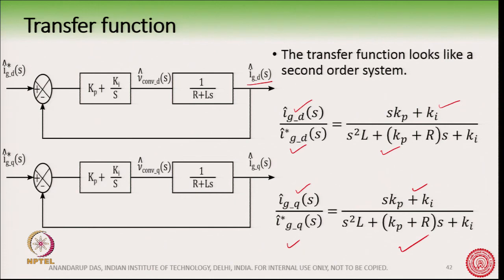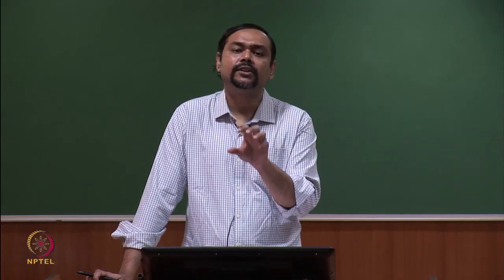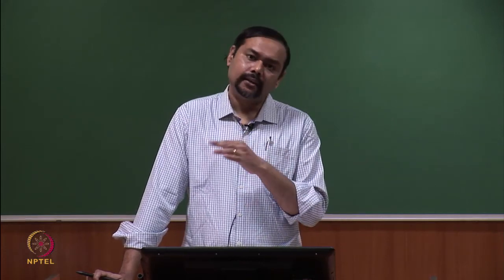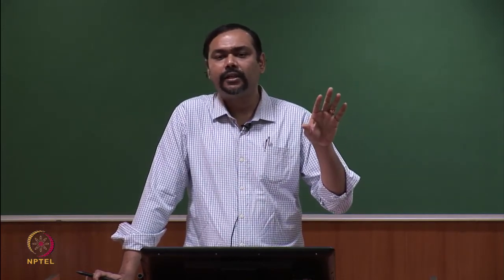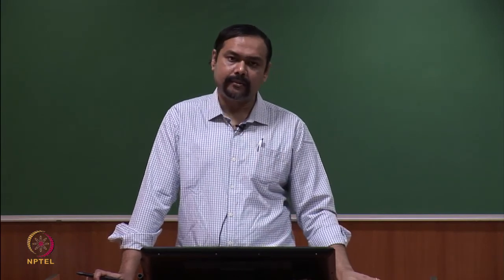So, we can go one step ahead and go into a DC domain with the help of the Clarke and Park transformation, and with that DC we can apply our linear control system theory. We give a small AC perturbation to these DC quantities, get a small signal model, apply the transformation and get it back into the 3 phase AC quantities, by which we can control the VSC.